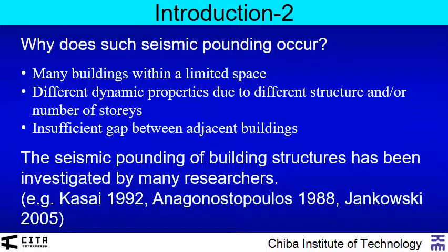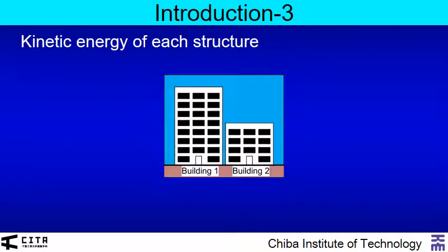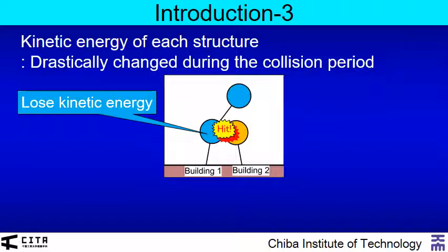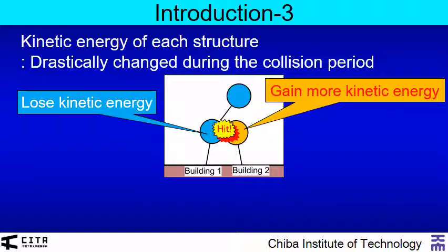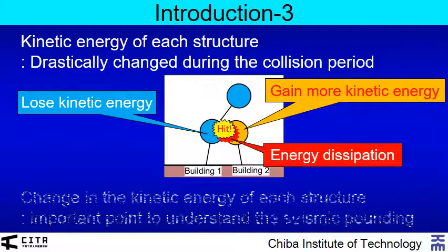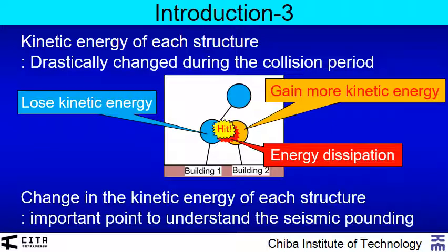The seismic pounding of building structures has been investigated by many researchers as shown here. During seismic pounding, the kinetic energy of each structure is drastically changed during the collision period. One structure may lose kinetic energy, while the other may gain. Energy dissipation also occurs as a result of non-elastic collisions. Therefore, the change in the kinetic energy in each structure is an important point to understand the phenomenon of seismic